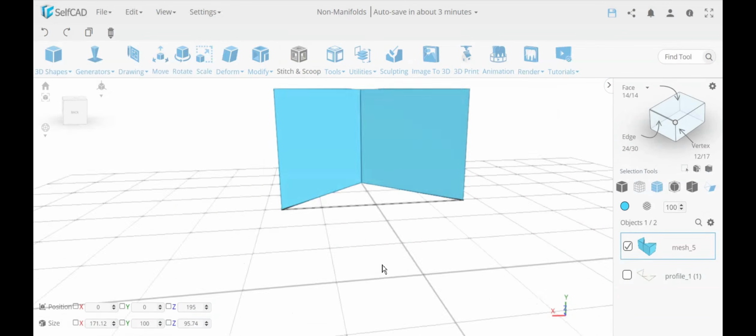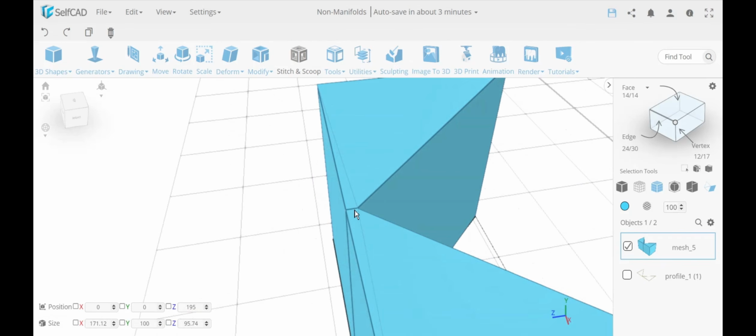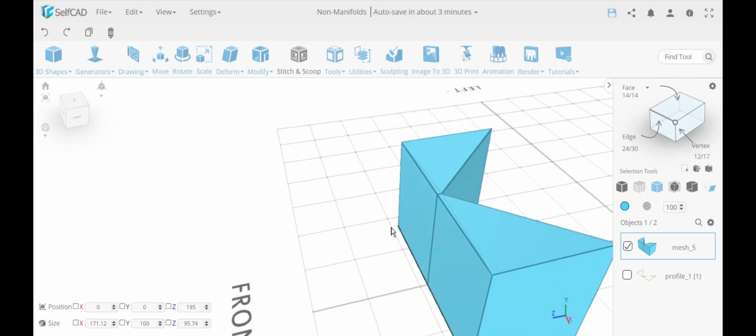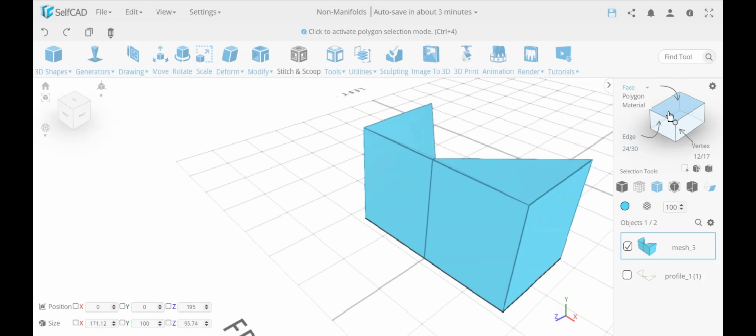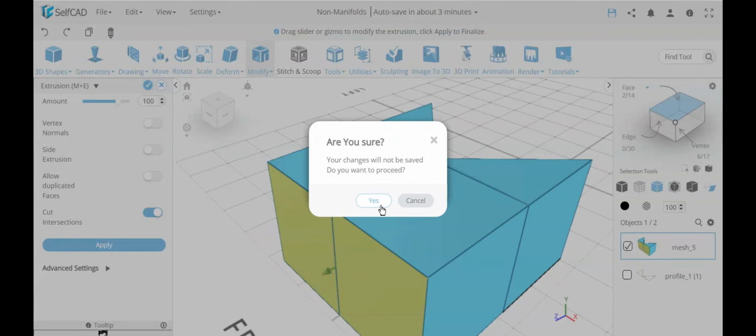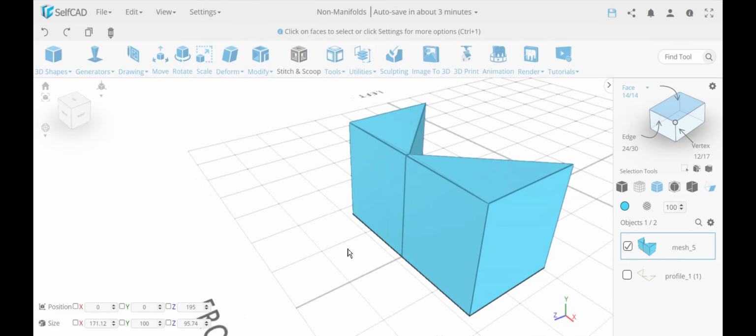And in this case, look at what I got over here. We got a beautifully manifold because it added this volume over here, and now it will not give me any issue. Now technically you could have extruded the back to do the same thing, just extruded this part, add an extension. But in that case, first of all, the extrusion, if you have only this one edge that's not manifold, may sometimes misbehave. But even if you get it to work, there's ways to make it work, it will change the design.